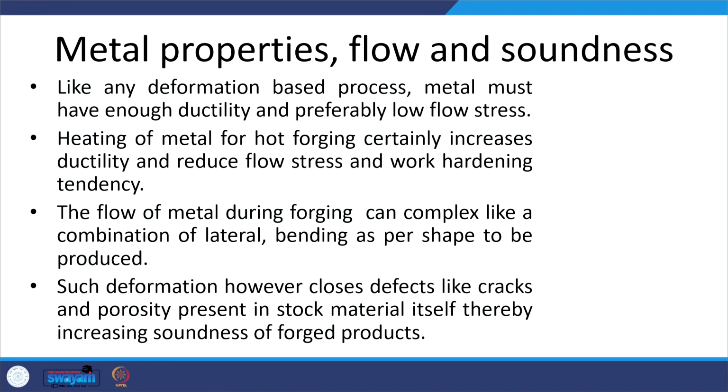We know that when the metal is heated to a higher temperature, because of recovery and recrystallization, the metal gets softened, ductility is enhanced, flow stresses are reduced, and the work hardening tendency is eliminated. That in turn facilitates the forging.